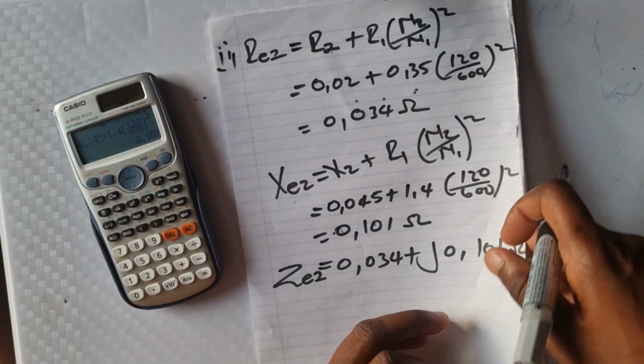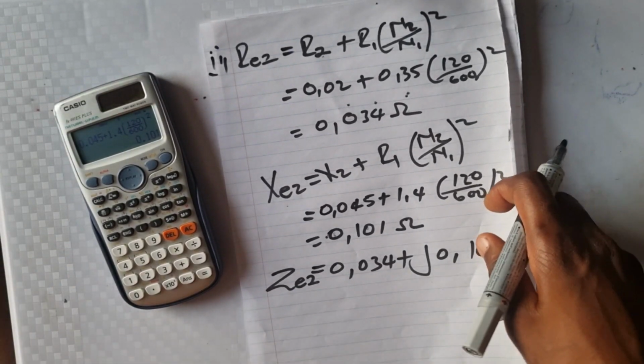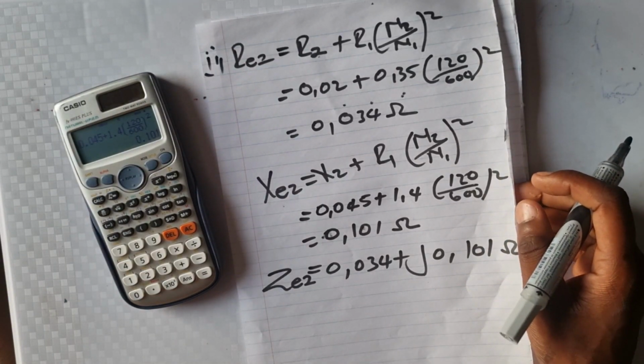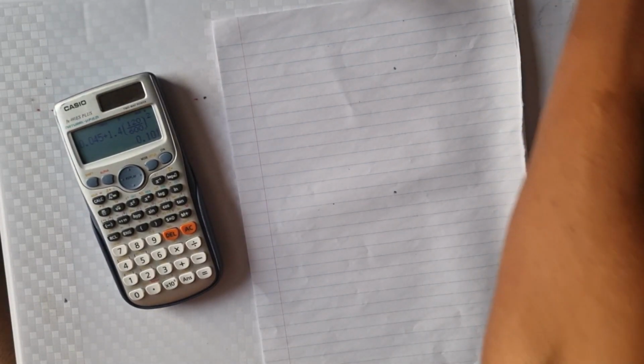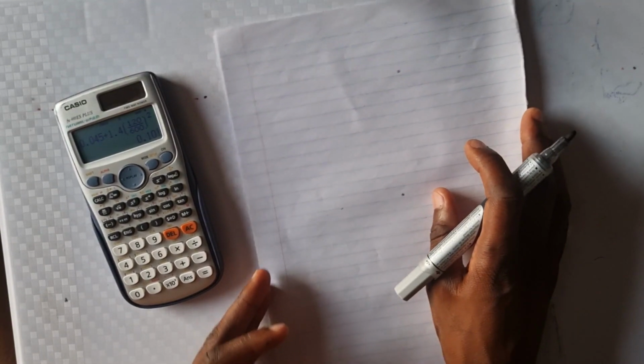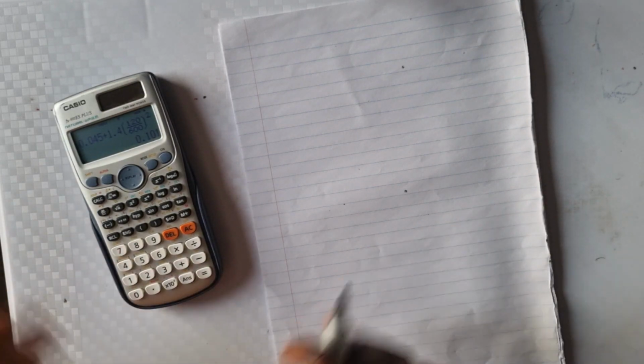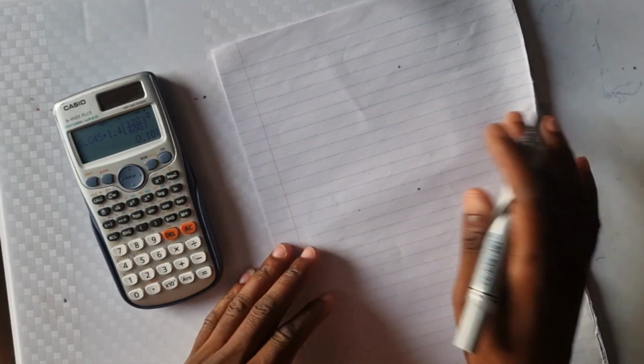So now the regulation is going to be the same whether you are using the primary or the equivalent referred to the secondary. Whichever you prefer or choose to use, you are going to get the same answer. So you just have to choose the one that is simpler. For example, here we are already given the primary voltage, so there is no need to calculate and use the impedance referred to the secondary, because then we would need to calculate the secondary voltage and calculate I2 as well. So the calculations are going to be more. If we are only referring to the primary, it's going to be easy because we already have V1.